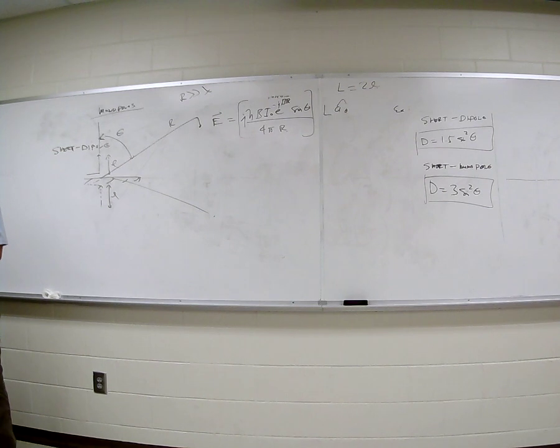What I want you to take note of is the resistance at the bottom. For a half wave dipole, an ideal one, it's 73.2 ohms, isn't it? What is it for a quarter wave monopole? 36.6. Exactly half. You with me? So the radiation resistance will come down, because it's a quarter wave monopole, not a half wave. The length of that monopole is really just half of a full dipole.